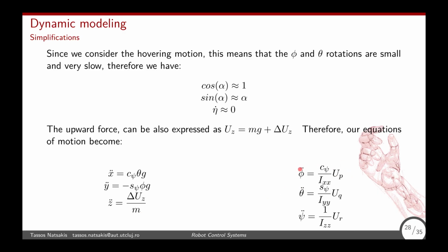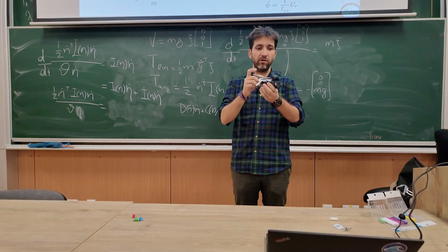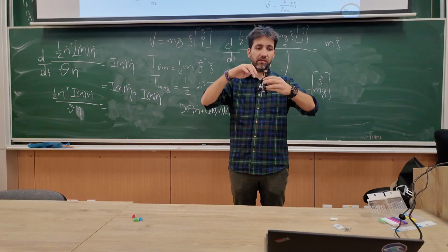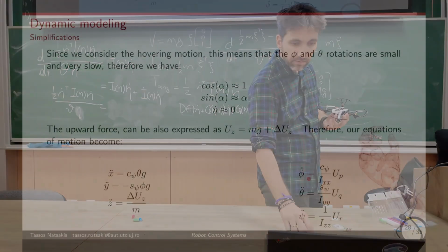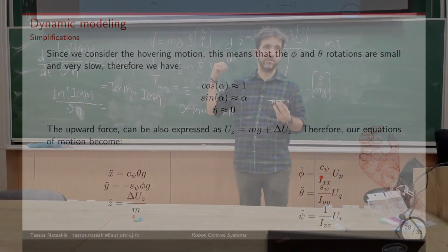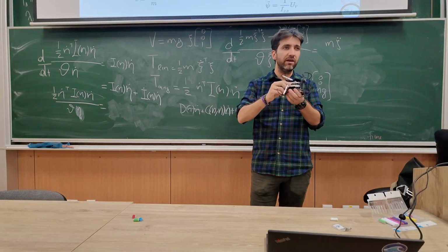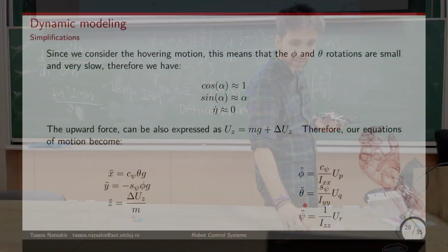Then here I see that basically the angular acceleration around phi and theta will be proportional to the torque I give in those directions. Again, makes sense. And here I divide with mass. Here I divide with the part of the moments of inertia that plays there, like the x, for instance, or the y. So again, some inertia around that axis. Right, and it's the same for psi.